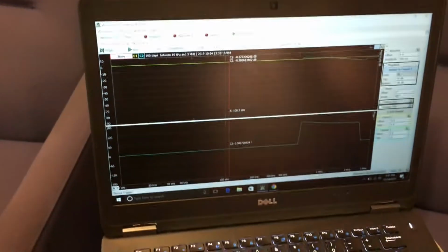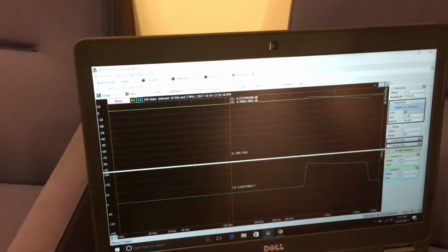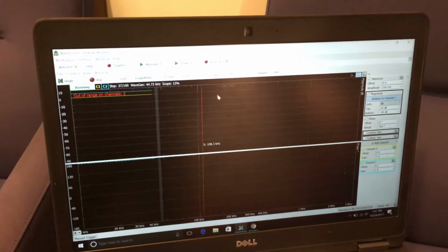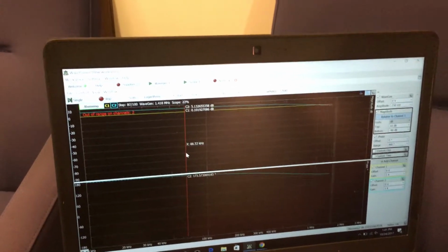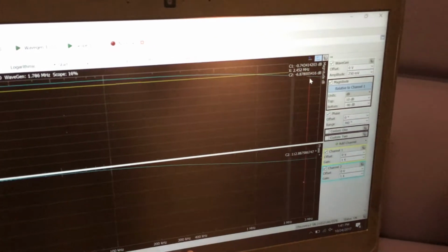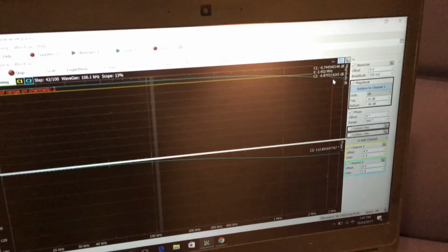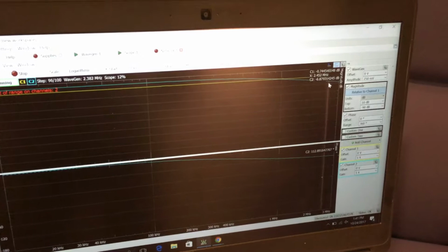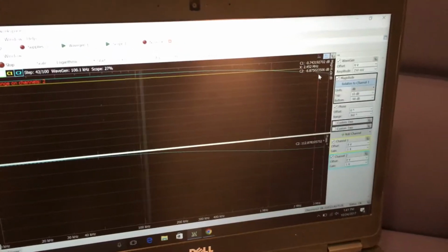And then for our network sweep, you can see over here from about 10 kilohertz to 3 megahertz, our value stays up and then starts to go negative over here because the circuit can't keep up with the rate of the data coming in, or it can't refresh itself enough during its operation.